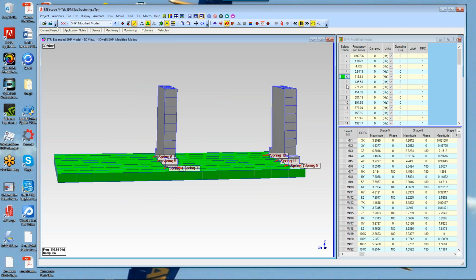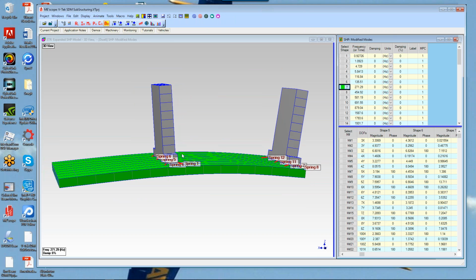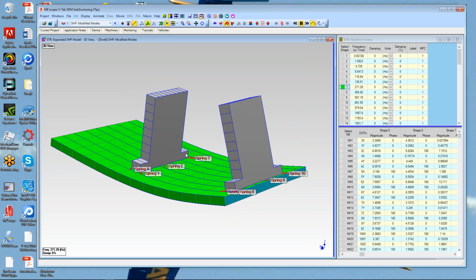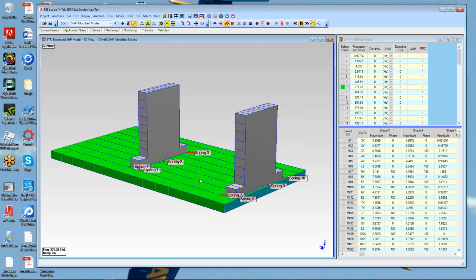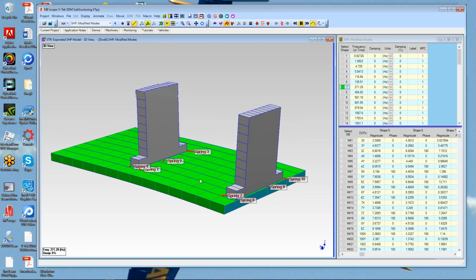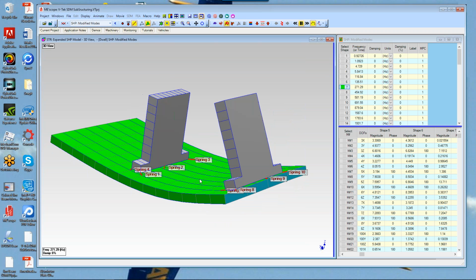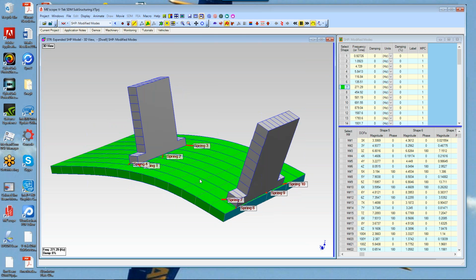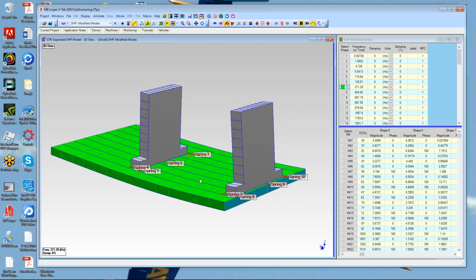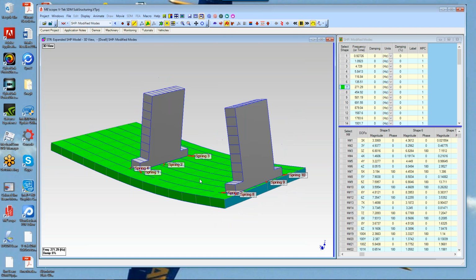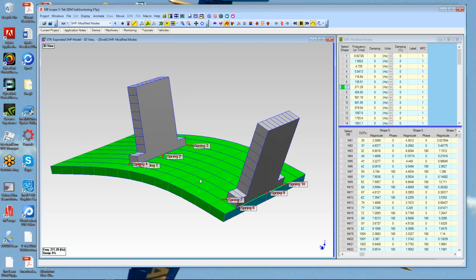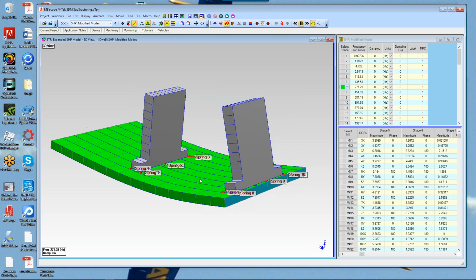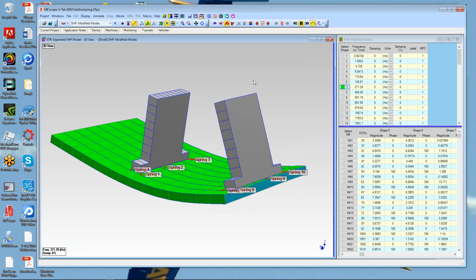That is substructuring. Let's go on now. I'm going to open a second project where we use this particular FEA model of the base plate and the two bearing blocks, and we're going to use it to animate the machine model, the VTech machine model. We're going to expand the experimental data using this FEA model and then use interpolation to animate the machine model.